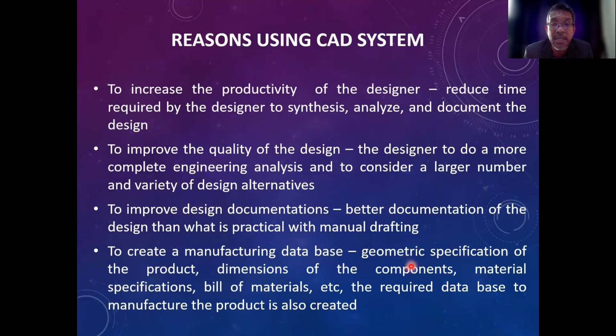And then we can also create the production database, for example, for computer-aided manufacturing. We can create the geometry or the coding for the specific product, components, design, and material. So when we do the manufacturing, we can just follow the manufacturing data, and then we can produce the product with the specific machine, at high quality, and can produce it within the lead time and the quality given by the specification.